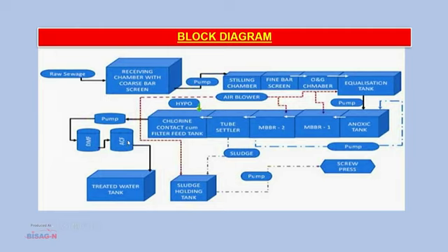Then stage 16, Sludge handling. Sludge produced in the system will be transferred to the sludge holding tank from the bottom of the tube settler through a pump. Sludge is pumped to the screw press sludge dehydrator for dewatering. Polyelectrolyte is dosed to enhance the dewatering efficiency.